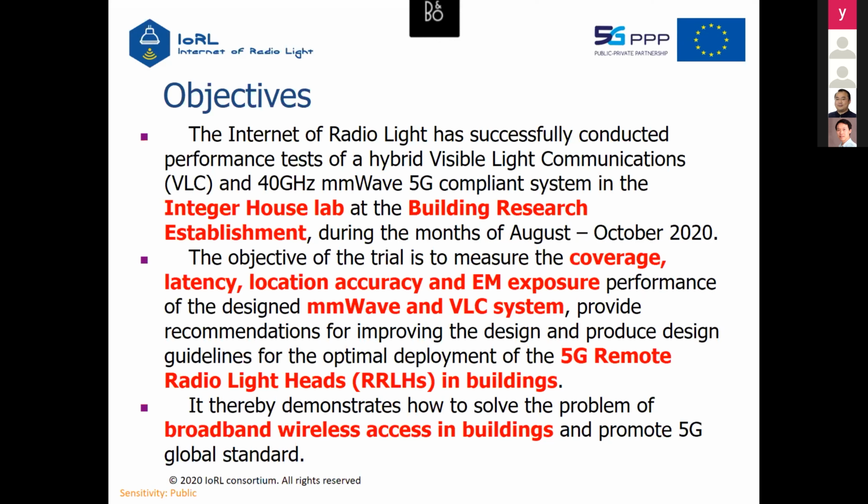And so the whole system is set up by the 5G RAN. This is based on the O-RAN base station and DU plus distributed remote radio head. And the receiver will be conducted at the Viavi test UE. So we have all the necessary measurements, including the EVM and the power, and also the power distribution or EVM distribution. And also we can have the CRC decoding and also the application data as well.